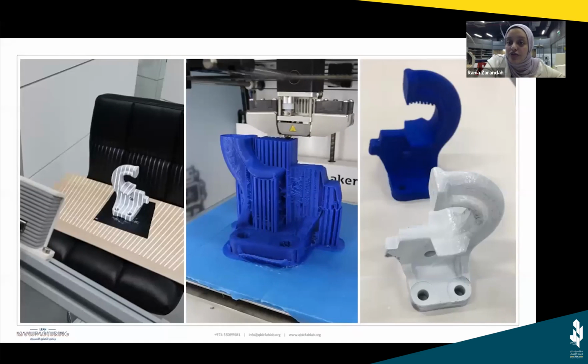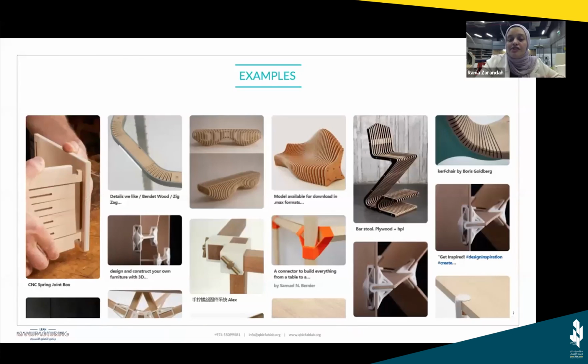These are examples of a 3D scanning process. This customer had a car hook and wanted to readjust the piece itself. So we 3D scanned the piece for him to digitalize it. Then he did a further adjustment to it, and then printed it back using a plastic FDM machine. So you could see if the adjustment he required was met, or if he needs to do a further adjustment to the file.